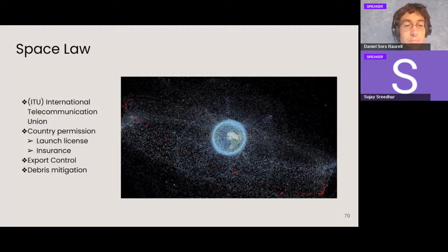And very importantly, the debris mitigation regulations. You have to work on a space debris mitigation plan and a space debris mitigation report. You have to comply with the 25-year lifetime requirement. Essentially, after your operations, you have to deorbit to re-enter the atmosphere, especially for low Earth orbits, within 25 years, so below this 25-year requirement. This is quite easy with small satellites in low Earth orbit because normally they naturally decay.